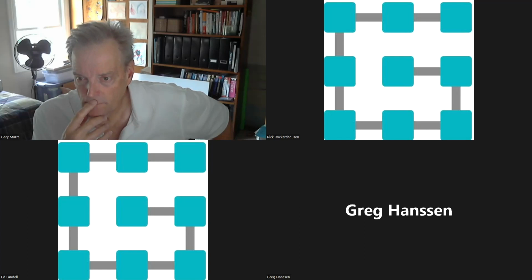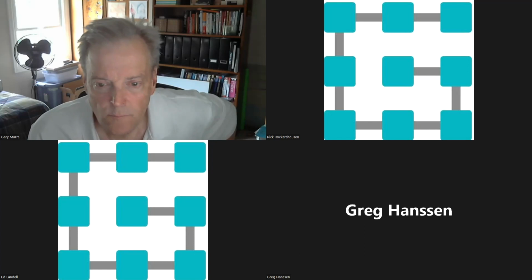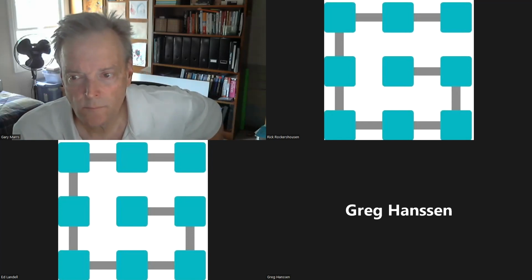I still can't understand how the vehicle was not acknowledging the messages. I mean, ultimately the solution was to add yet another node to the bus, which would acknowledge our own messages, because no one on the vehicle seemed to be acknowledging. So I don't know, it was just a really weird situation. And I've been playing with CAN bus for 15 years and I've never encountered that before.